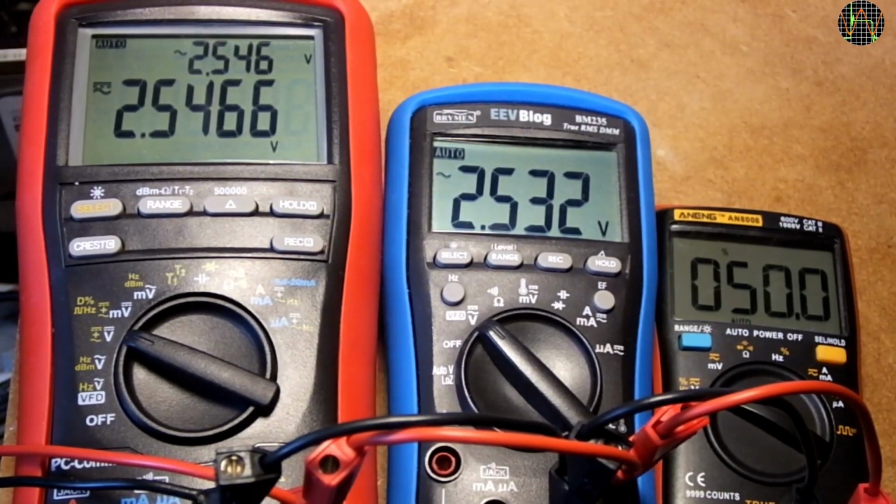The proof of the pudding is running the same test again, but this time the multimeter on the left is showing AC plus DC in the main display. The small multimeter on the right is again showing the duty cycle. At 50% duty cycle we have no DC component and everything is showing the same AC value within tolerances. At 60% duty cycle we see the expected drop of the AC, but the AC plus DC value stays the same. The same at 70%, 80%, and 90%. The AC value has dropped by more than a volt, but the combined AC-DC value is still the same.